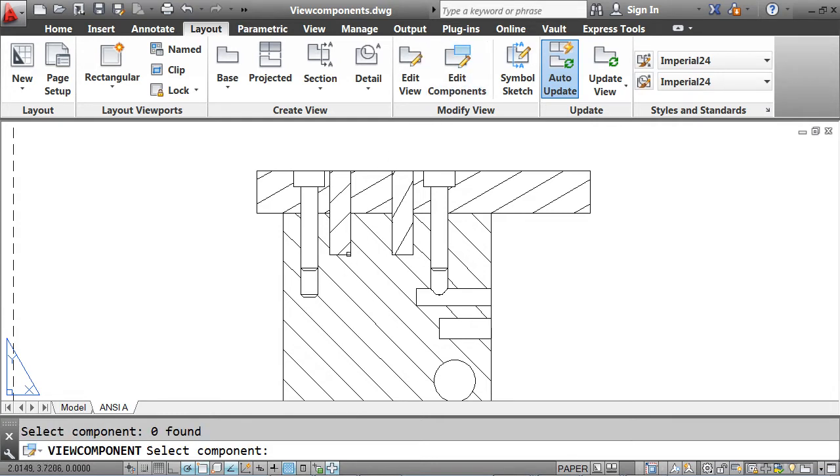I'm going to create a crossing over everything here. Hold my Shift key down and select the edge of that steel plate that's on the side. As I select that, the plate goes away, and then press Enter and None, and the crosshatch goes away. Let me do it one more time.